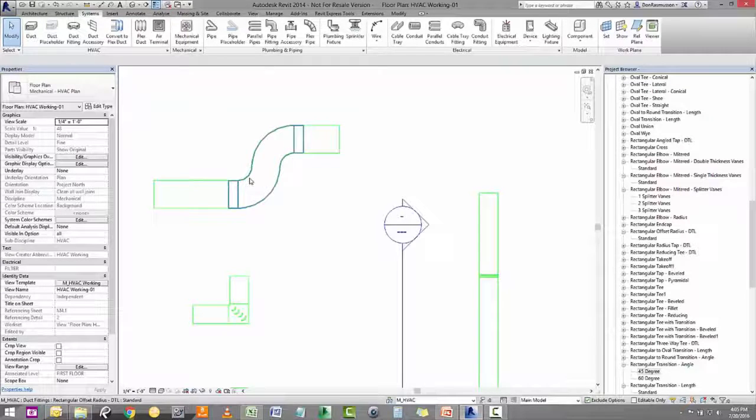Now, this geometry, as you see, just kind of stretches north and south. It doesn't necessarily stretch east and west, and the dogleg isn't exactly accurate either. But it's something that we can use in Revit that's going to use our analytics and make your analytics a little bit more accurate than if you used three fittings to complete this, being an elbow, a straight, an elbow, transferring that all to one fitting.